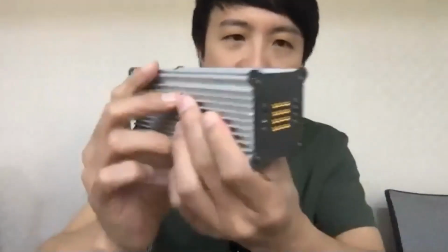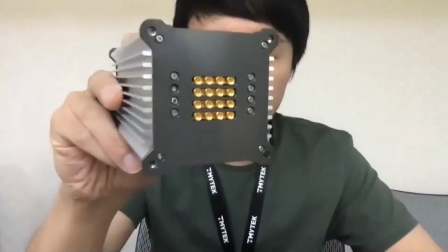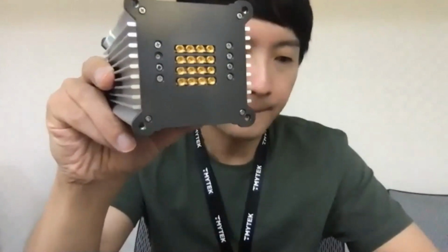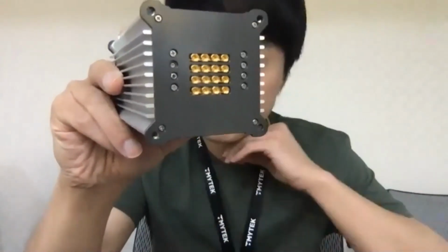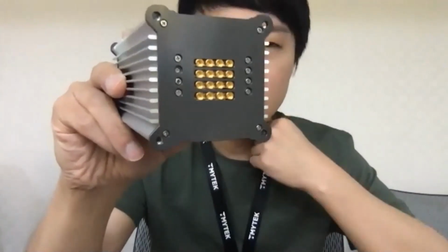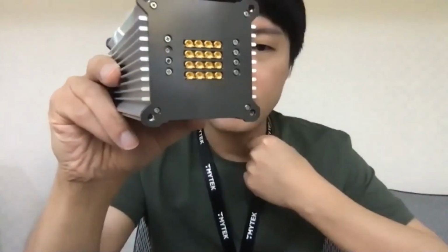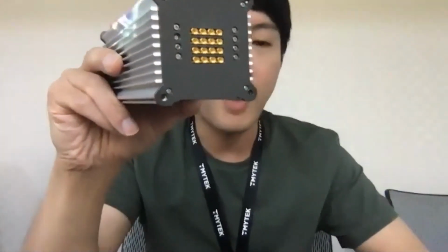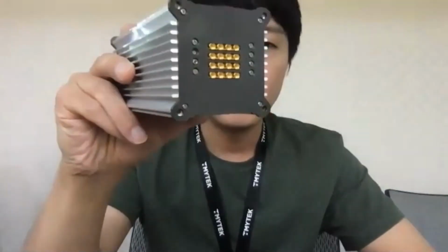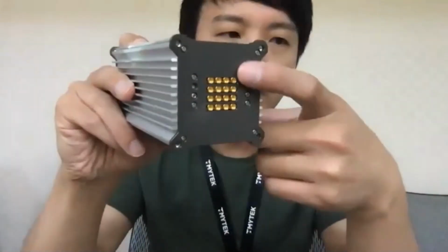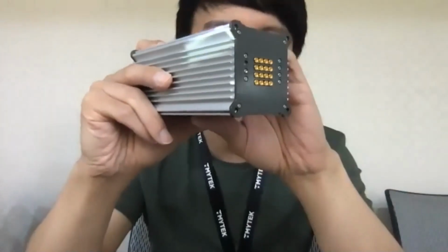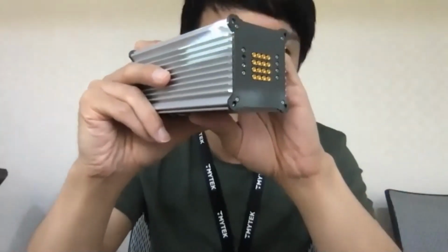Usually, as you can see here, we have 4x4, so there are 16 RF ports. That means we have 16 sets of PAs and phase shifters. So in this case, to maximize the steering range, we need to use one RF port to control one patch. One maps to one, and in that case we have the widest scan range.